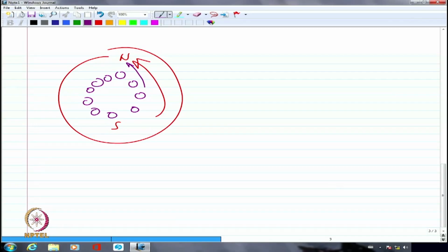If it needs more rotor current, the speed will decrease, because of which the relative velocity will increase. That relative velocity will induce a larger EMF. Because of larger EMF, there will be a larger current and there will be a balance. That's what happens every time you load an induction motor. We'll talk about the loading mechanism further.